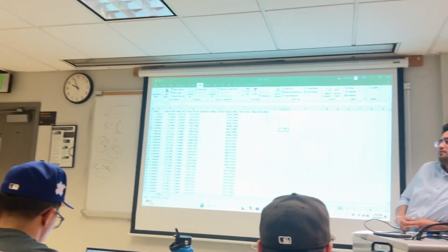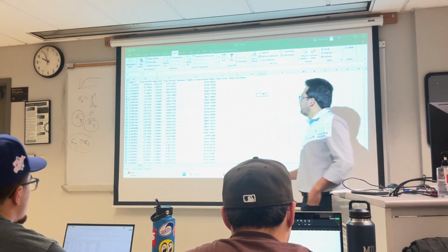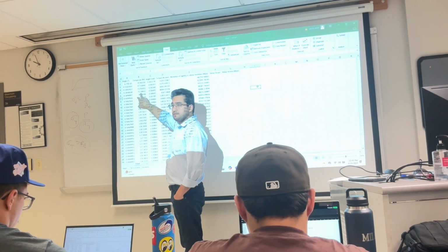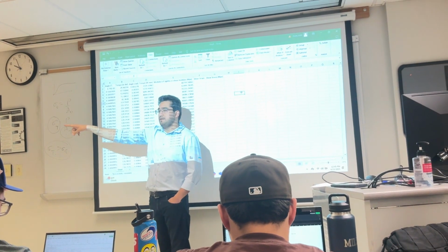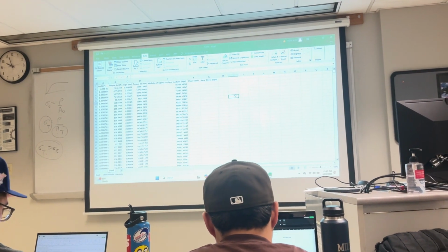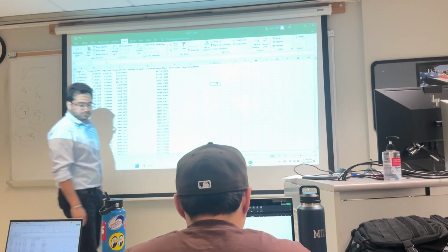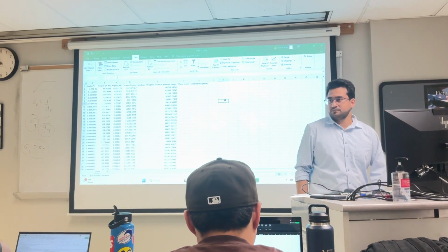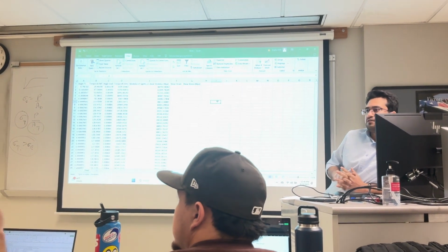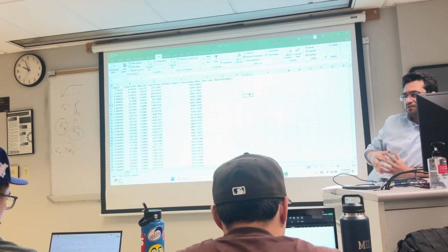How do you get the torque again? Torque is force times distance. Torque is given, you just have to multiply this column with the 113. In here I explain why I multiply with 113. Okay. Did you gauge it, right? For the strain, is it the gauge length or the full length? It's only the gauge length, always, because that is a gripping section. You know, it goes inside the chuck.